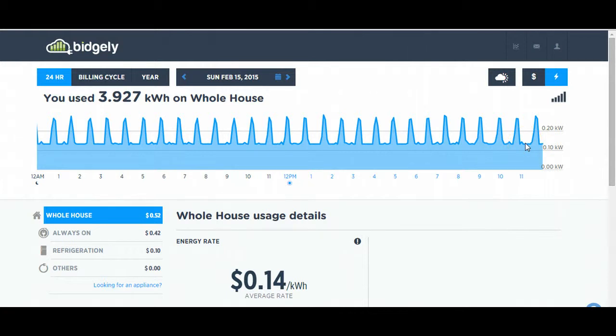The next step would be to go around the house with something like a kilowatt meter, which is a little device you can plug in and test the power usage of individual appliances. Start plugging that in to see what it is that's actually drawing that power. I don't have a home automation server or anything running, I'm just using a Raspberry Pi. So it's probably my entertainment system or something like that that I could safely shut off, especially going on vacation, to drop that real-time usage even lower when I'm there.